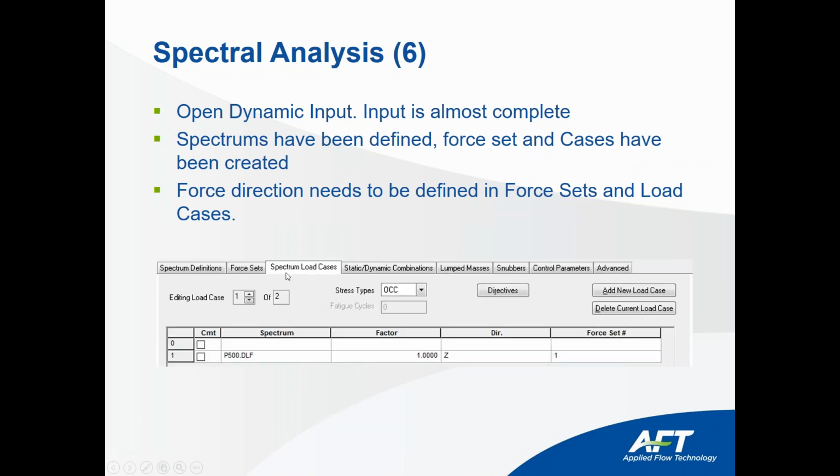So now, let's go to the spectrum load cases. The spectrum load cases are created so you can combine them with the static load cases. So here it creates for you the first spectrum load case using the DLF curve that is applied in node 500, which is in the horizontal. Factor 1, you leave it that way because it imports the real forces, but you have to be careful and change the Z.